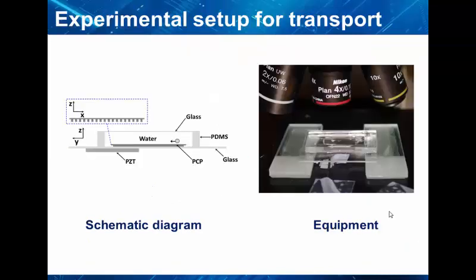According to the above simulation, and in order to combine with microfluidic technologies, we developed the following chip system. It consisted of a cavity made of PDMS, an offset PZT4 acoustic source, and a phononic crystal plate inside the cavity. The whole system was integrated on a piece of glass, and the results can be observed and recorded by a microscope.